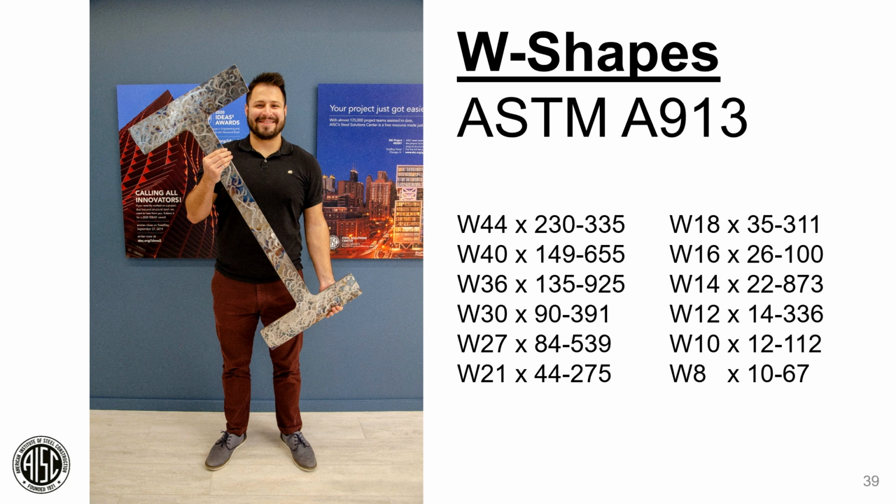I want to make you aware that not all of these shapes are rolled by all of the mills, and they might not all be readily available. So before specifying ASTM A913 material, make sure you check with your local fabricator on the availability of that material. And there is a premium for A913 material as well. So A992 will be cheaper than A913.